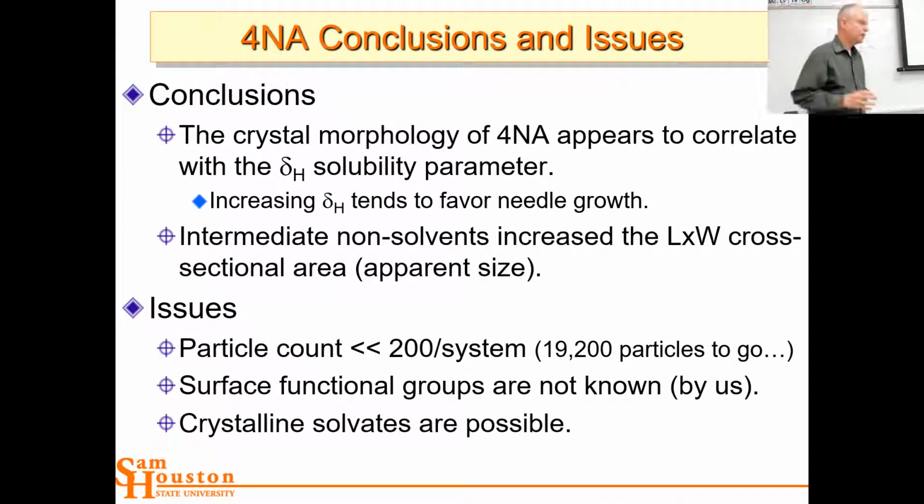And so our conclusions: the morphology seems to correlate best with the Hansen solubility H parameter. Increasing H should favor needle growth. Now, does that mean that's the better crystal habit? Maybe not. Maybe for your process you want gravel and not needles.